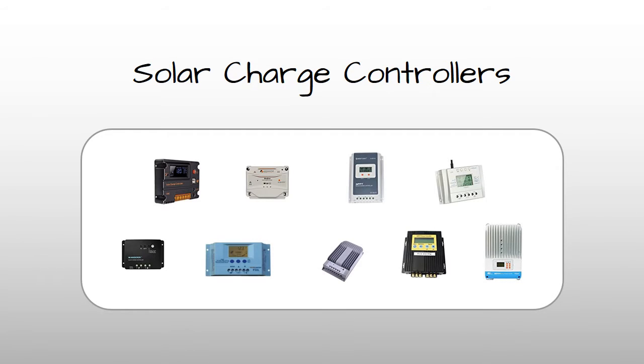Another way to charge batteries is by using solar energy, and for this you can use what are called solar charge controllers. Solar charge controllers operate differently than solar inverters. Unlike solar inverter systems where the goal is to send AC current to the grid, the goal for solar charge controllers is to use the DC solar energy to charge 12 or 24 volt battery banks. Like the solar inverters, they control the MPPT, or maximum power point tracking, to extract the most electricity from the PV panels. Not only do these units control battery charging, but also the load discharging as well.